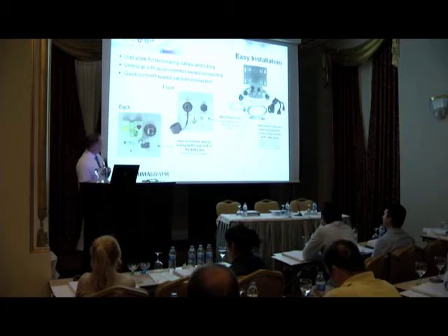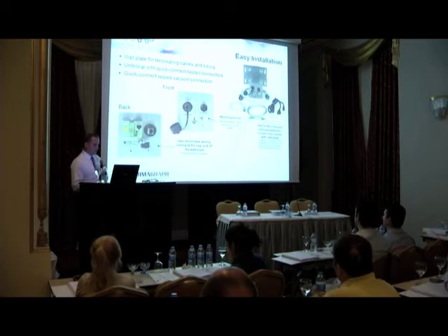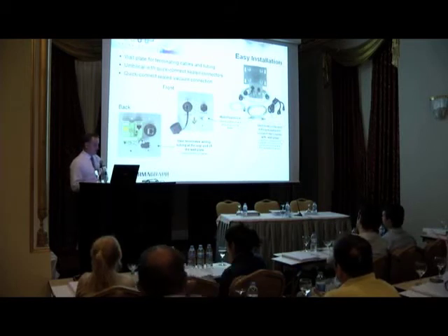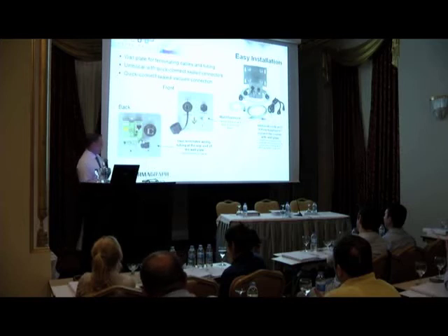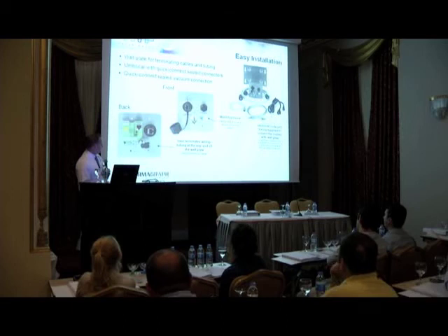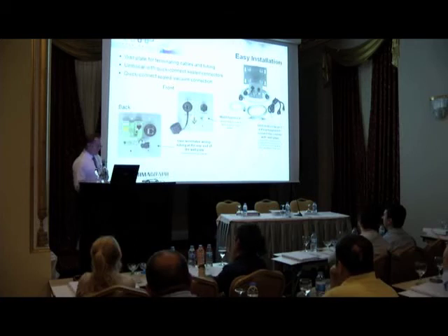So it's all very well having your particle counters in the clean room. Obviously the particle counters need a vacuum, if they're not an integrated pump solution such as the 6015, they require vacuum and data. So the easiest way to do this is to provide a wall plate for your data and for your vacuum here. And these are designed to pretty much look like a power socket on the wall. So you plug your vacuum and your data into your facility.